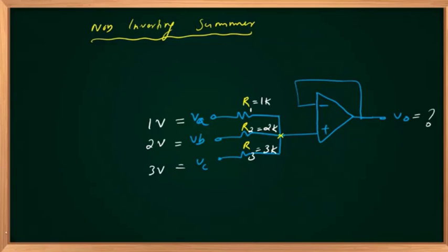First point is to identify the feedback. Feedback is negative. V plus equal to V minus. V minus is connected to V out. So this will be V out. This also will be V out, and V out is unknown. Our 3 branch currents here are I1, I2, I3.